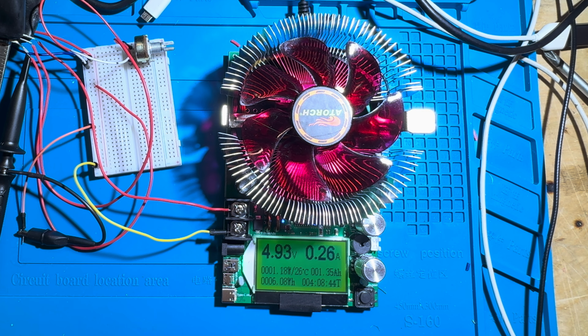So we are really in that middle regime of the MOSFET. Typically you want to provide 0 or something like 13 or 14 volts to turn it on or off. We're in that middle there. We're driving the MOSFET in its linear regime. It's dropping 7 volts and we're seeing 5 volts across our load at 0.25 amps, or 250 milliamps.